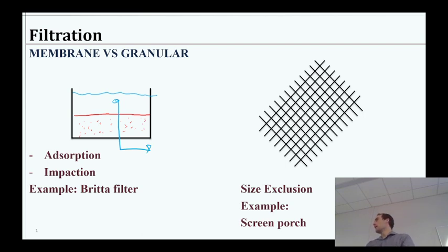So that's the plan. It's essentially just like groundwater, right? Groundwater is constantly moving through porous media, whatever sand or gravel or soil grains there is. And in our water treatment case, we just carefully control it and make sure that we have good, precise control of what kind of media there is, that it's not going to escape and contaminate our water or clog up the pipes or whatever, and that we have good control over it so we can properly clean it as it accumulates dirt. So when we think about granular filtration, then it's not actually a matter of size exclusion.